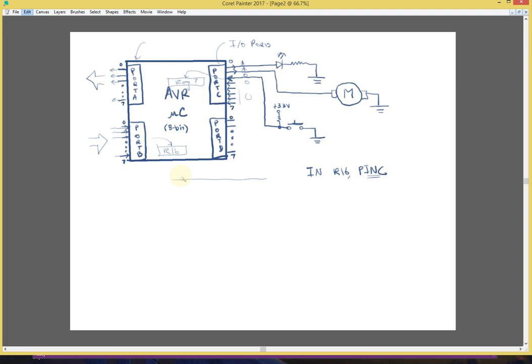Alright, so we have bits 0, 1, 2, 3, 4, 5, 6, 7. And this is R16. What's going to happen is that we're going to get the current value for these 2 in the output. So this is going to be the value for the output. If you have these 2 on, then you're going to read 1 1 because you're reading what the output is set to. But for the rest of the bits, you would actually read whatever is on the inputs.